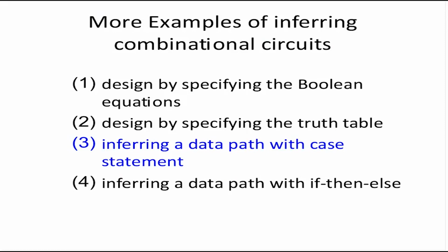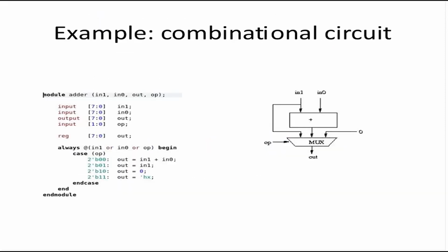However, you could force the usage of a mux by using a very special coding technique, which I will discuss in the next lecture. I'll discuss how to make sure that this code here gets translated into a mux. Many times we would want the tool to implement a mux kind of structure due to very specific needs, and we could do that. So here also the reg is not a register in hardware, obviously it's a wire, because this is not sequential.